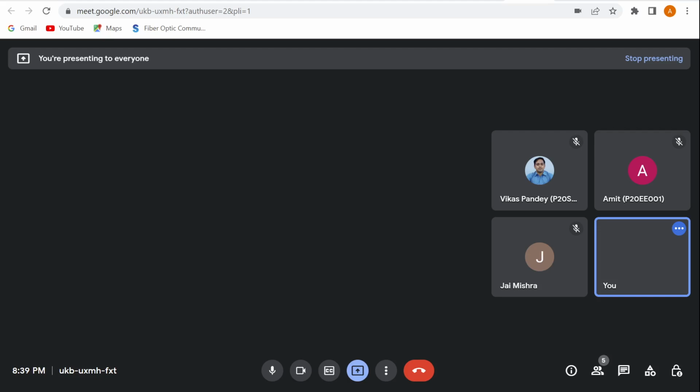So X(w) equals the integral from minus infinity to infinity of x(t) e to the power minus j omega t dt. Omega equals 2 pi f, as we already know, so either you put omega or you can write 2 pi f. The time period we take is from minus T by 2 to T by 2, and because x(t) equals 1, this is the integral of e to the power minus j omega t.